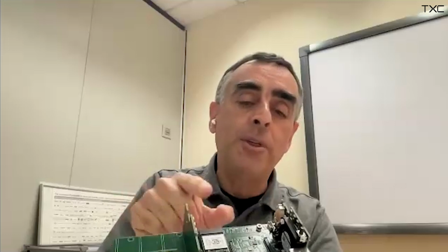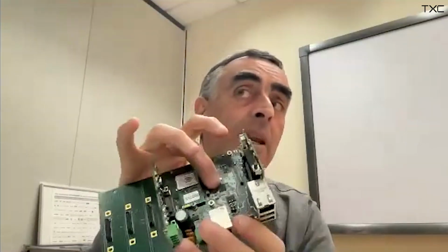And this one serves basically as the house master of the thing. It controls everything, controls the watchdog, it controls the expansion boards, the power to the expansion boards. The I/O of the expansion boards can go through the RP2040 or to the Raspberry Pi. It's your choice. So you can do a lot of things taking advantage of the RP2040 itself for, let's say, low-level processing of I/O, if you want. So it's pretty flexible.